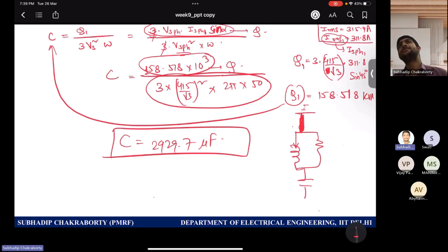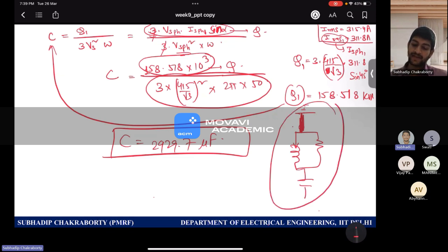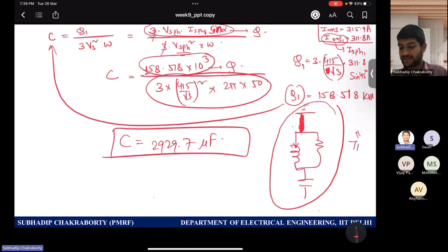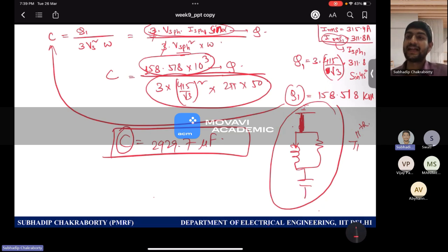So when someone tells you nth order high pass filter arrangement, then it is a single sub-layer only, but the threshold they are giving you, greater than or equal to, high pass means higher than or equal to, so the one only. So that's why you don't need to divide C by 2 or 3, because if it was another layer providing 11th and then 5th and then another high pass filter layer, then all those capacitors would have participated, just like the previous problem.